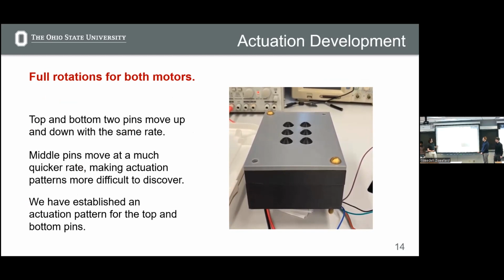But what we needed to find out next, we have the layouts for both the top and bottom pins, as the cam profiles are the same. The issue is the 2 pins in the middle. They occur at a higher frequency in relation to the top and bottom pins. So we need that finer granularity of the larger stepper motors, and sometimes even finer than that.